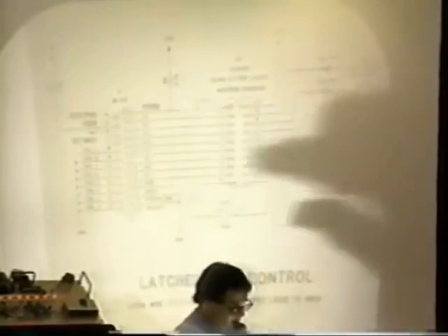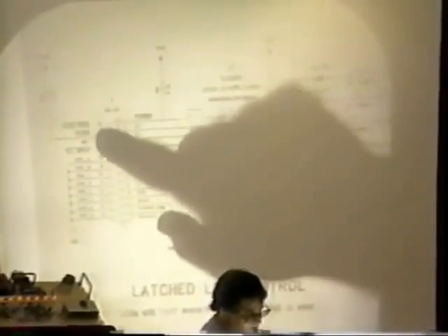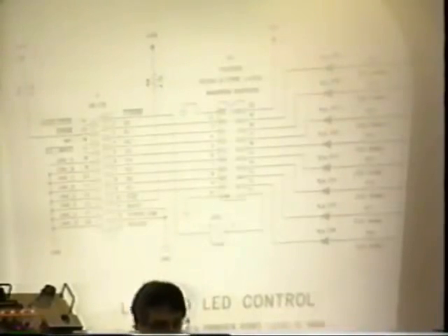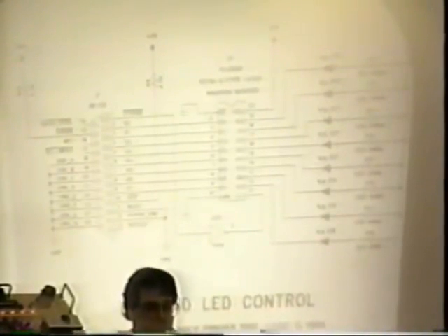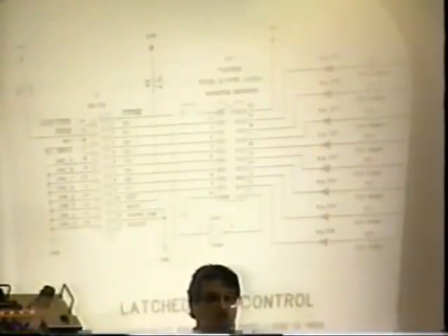That's right. You're bringing in the 8 bits on what says acknowledge, busy, paper, select, error. In it, you have 9 input lines, and you're really reading it in 2 nibbles at a time. So you're reading in 4 bits and 5 bits. So it's a teeny weeny bit slower than all at once. Some of the portables, of course, have bidirectional ports, but that doesn't matter. So it's a little bit slower, but it's still a lot faster than serial, and a lot less money to build the converters.